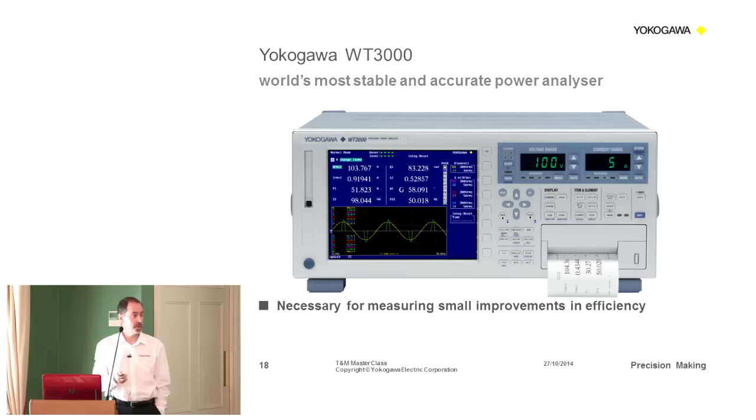So it sort of forces you within the one instrument to be able to measure both input and output of your inverter in order to look for these small changes of efficiency. So that really forces you to go for the highest accuracy that you have available.